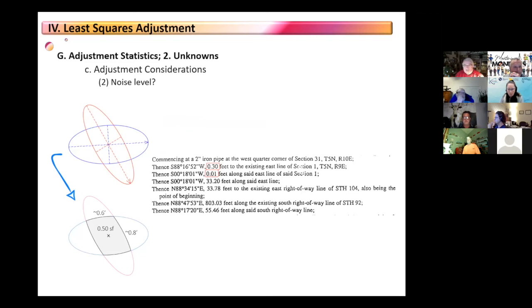So when I've got a distance of 0.3 feet, if that's within this area here, that's great. That's within the uncertainty of both of those surveys. So that's zero as far as I'm concerned. That doesn't exist. And that 0.01 feet definitely doesn't exist, let alone the fact that if you ever tried to measure 0.01 feet at a particular bearing with a total station or whatever, that's a heck of a challenge. Try that. That'll be your other homework assignment for this weekend: go out there, lay out a 0.01 foot line at a specific bearing.